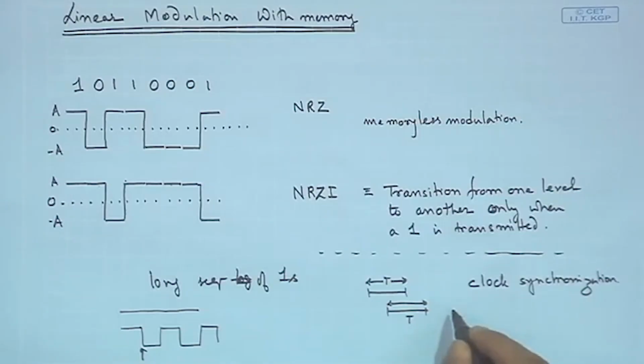So, then one could say that, well, in this case, if there is a sequence of zeros, then you have a problem, but of course, those could be handled in many other ways by mixing the zeros and ones, by XOR and many other operations. So, this is highly beneficial in clock recovery. There are many other techniques like the Miller code, and there are many others. We just show one of the schemes over here to identify how this works.